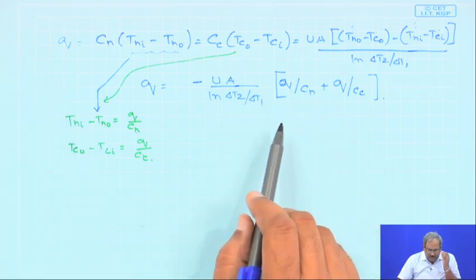See, the main purpose of this is to get rid of the outlet temperatures. Wherever Tco or Tho appears, through the use of the heat balance, we try to get rid of the outlet temperatures and see what we can obtain as an expression involving epsilon and NTU to express the heat transfer for such situations. So, I am not bringing any new concept except the maximum possible temperature difference, and which of the fluid is going to reach that maximum faster as compared to the other.